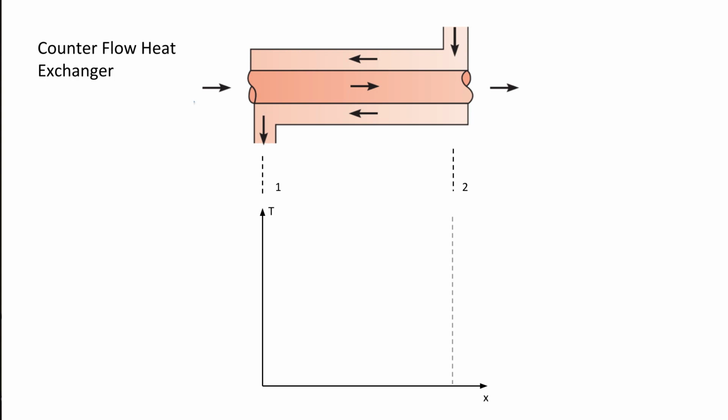So I'm going to make this schematic. And one of the reasons it's so important to do this is because very complex heat exchangers, we treat them as if they are counterflow. Just say, let's assume it's counterflow, and let's use a correction factor. And somebody already thought the correction factor is for you.